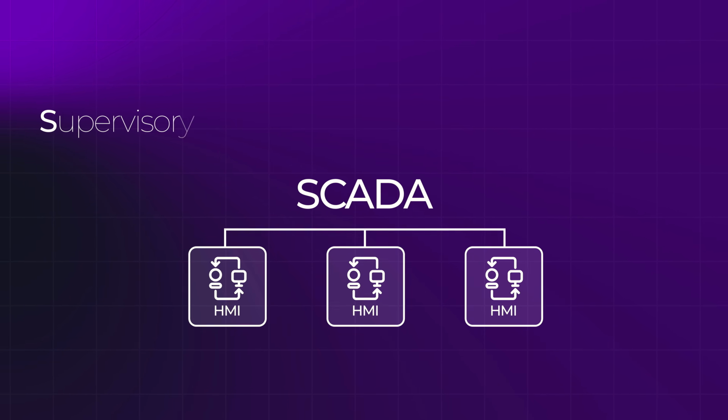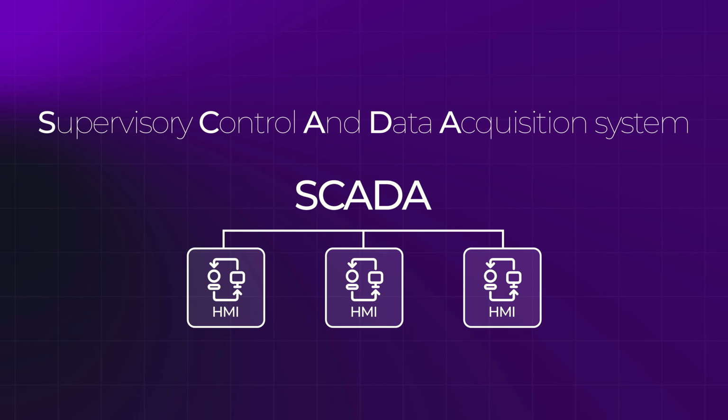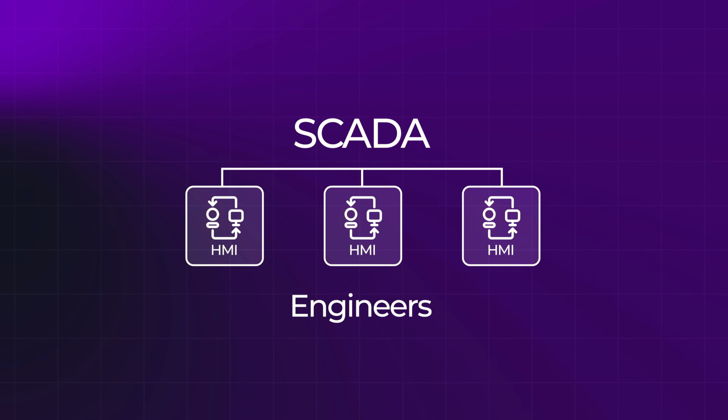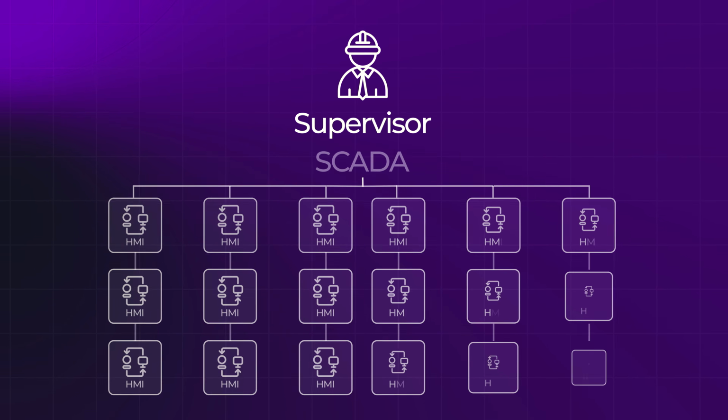And a quick note on the architecture for the engineers in the room. HMIs often sit alongside something called a SCADA, a supervisory control and data acquisition system. That can be a bit of a mouthful, but basically it provides site-wide visibility. While an HMI can allow engineers to control a single machine, a SCADA system can allow engineers to have complete visibility over potentially an entire factory or even multiple sites. It collects data from dozens, sometimes hundreds of PLCs, things like pressure, temperature, system states, collating all of that information into a single location. Operators and engineers can trend that data, set alarms, or even make adjustments remotely.